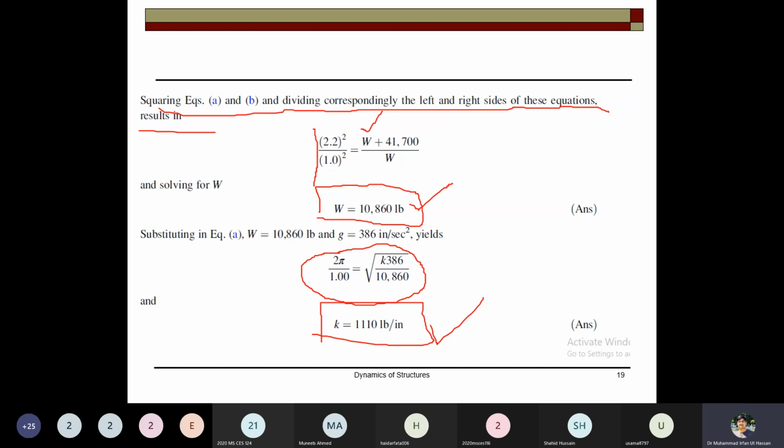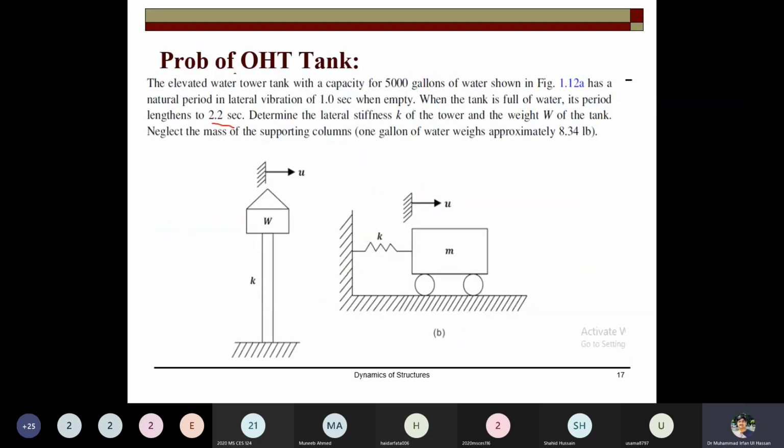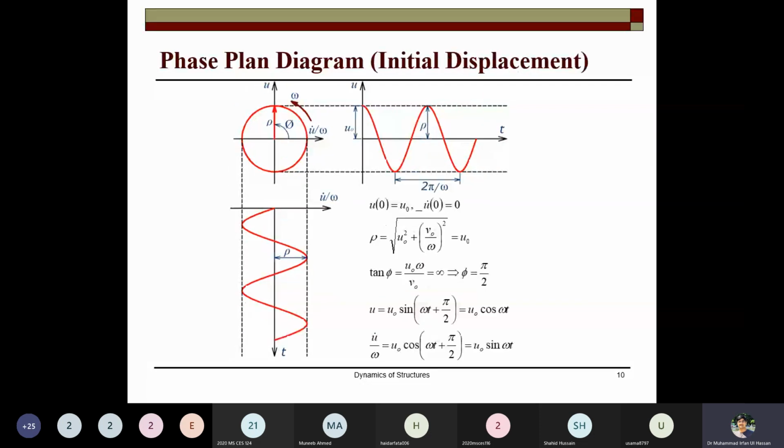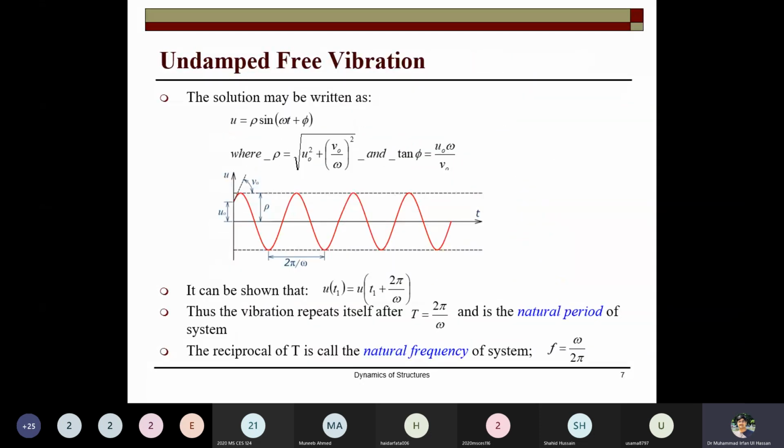So actually free vibration is very helpful, because any practicing engineer has an eccentric mass vibrator and they vibrate the building and take some readings of the frequency and the vibrations. They note down the values and then they are able to compute the stiffness of the different structural components. So this is the application that you are doing for this topic. These two problems are there, but you can see many other problems from the book also. These are also from the book by Mario Paz, and you can plot the response also. So try plotting the response of the system also.